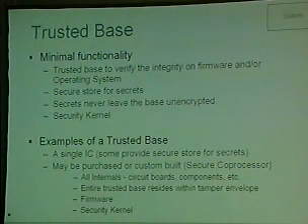You have it somewhat restricted to the die itself, and that really does take the attacks out of the hands of most attackers. But as you can see from Markus Kuhn's paper on the state of smart card security, he successfully, using fuming nitric acid and similar methods, removed all the protective epoxy and could actually do a die analysis attack. But I would have to say that that is a tamper-evident attack. The firmware can also be protected inside the trusted base, and you also have mechanisms that can verify the integrity of software that isn't necessarily inside of the trusted base.